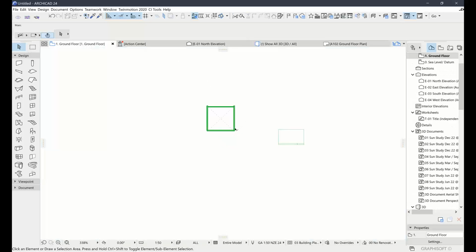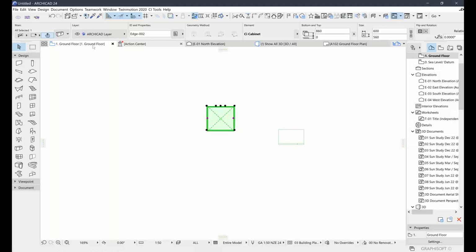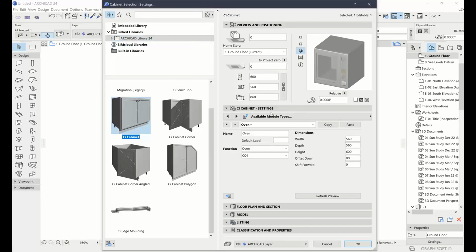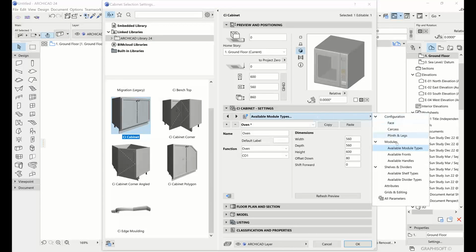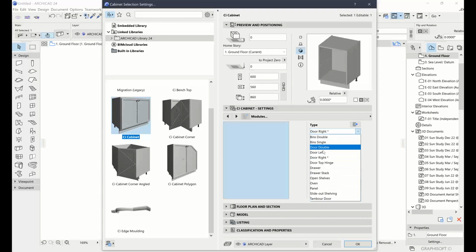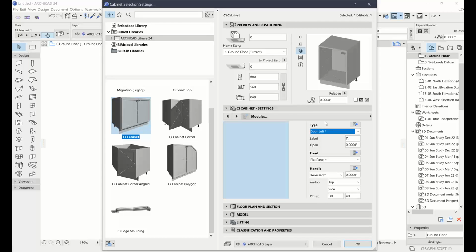Someone was saying that when you draw a cabinet, and you stretch it, it is creating repeating units at 600 as you go, which is the default behavior for the cabinet tool, but you can change that to do something else. So I'll just set this back to not my invisible custom door.